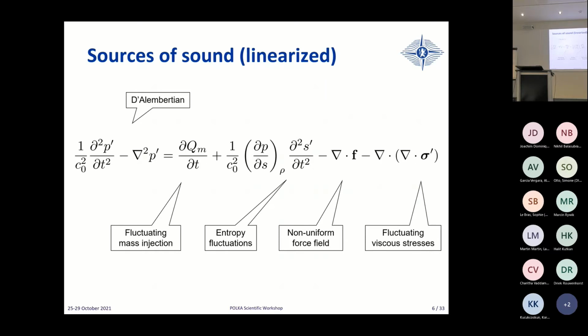So you can almost feel with your hands that this term in here, when it is related to combustion, of course, is going to be related to an acoustic monopole. Okay. Now, this guy in here is going to behave, so that's the non-uniform force field.